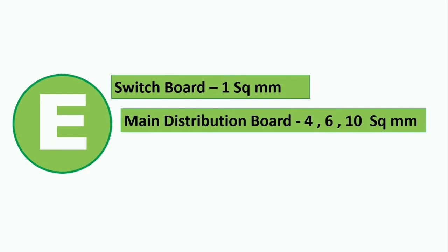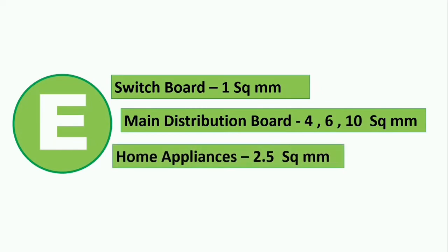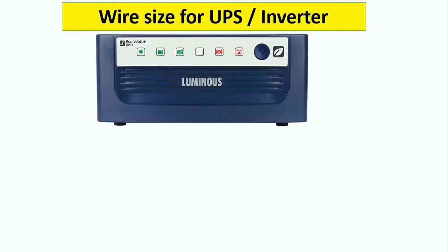Earthing starts from 4 mm when you are earthing a distribution board, a distribution point. You use 4 mm. On no account are you allowed to use anything less than 4 mm. While when you're earthing home appliances such as our basic socket outlets for our fan, for our dishes, our gas cookers, and whatever, you use 2.5 mm.